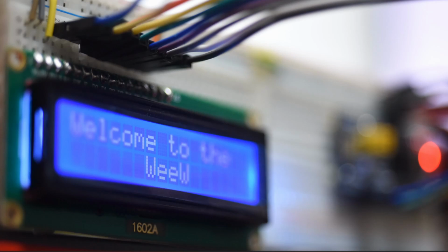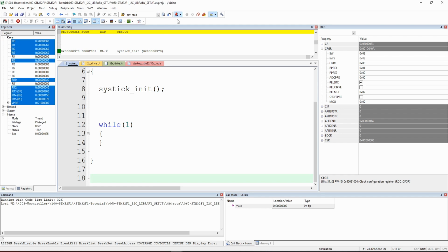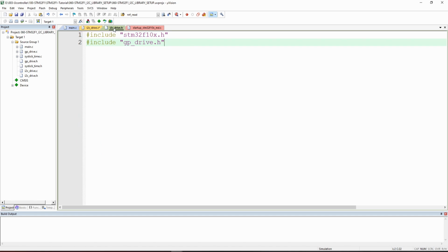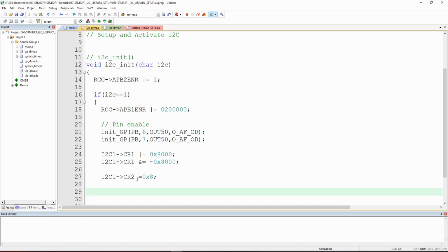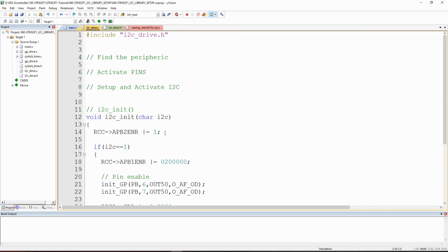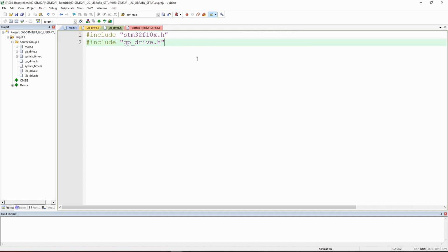Okay, so let's open back again and close. Good. So let's go back here. We need to divide the number that we have, 36 megahertz, by a certain number so we can get our code correct. So let's create 2 variables that we provide here as a define. Okay, define, and we call I2C fast mode, and it will be 0x2D. And the other one, let's just copy here like this, and we put I2C standard mode, not fast mode, and we put this one as 0x B4.